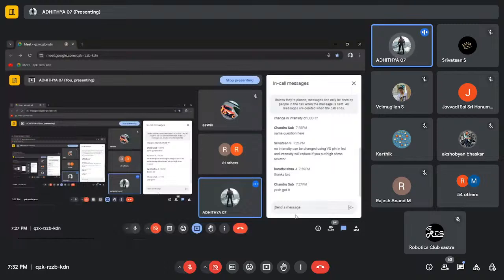Pin number 8 is the positive for the motor. So if you need to drive the motor at 12 volts, you have to give 12 volts to this. And then pin number 9 is again enable 2. Here the L293 has two motor drivers in a single IC.